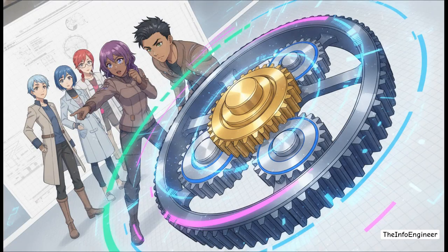If we want to actually engineer a sophisticated solution, we look at the planetary gear alternative. This coaxial design is beautiful because it eliminates the offset shafts completely. Since multiple planet gears are meshing all at once, they share the physical load simultaneously. This gives us unbelievable torque density and shock resistance. You can hit high single-stage reduction ratios, anywhere from 3-to-1 up to 10-to-1, and crucially, you can engineer asymmetric torque splits. Think of 40-60 rear bias for a performance all-wheel drive system done entirely through pure gear geometry.